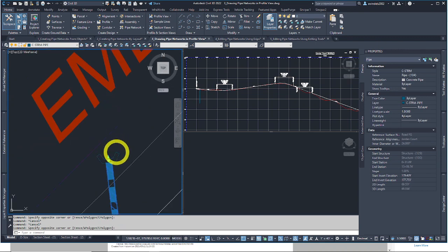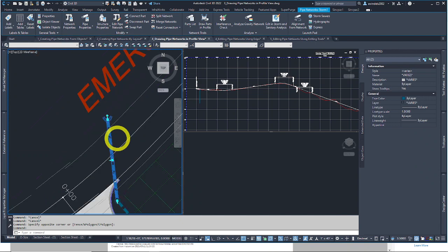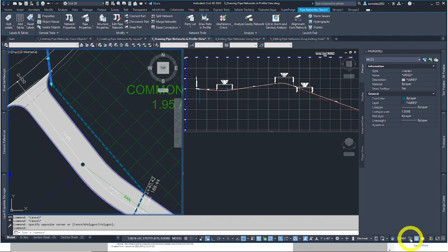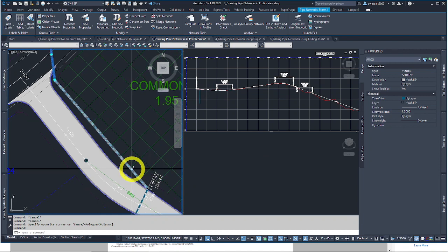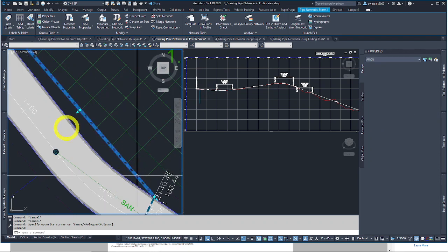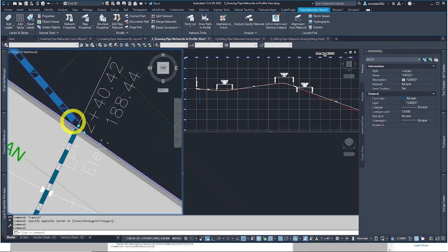It didn't really instruct you to add these structures and pipes, so I'm just going to see how it looks. I'm curious. Grab more pipes. You can use isolate objects and hide objects to more quickly isolate Civil 3D objects along with AutoCAD objects. That might be a quicker way to select a really complex network that's snaky and has hundreds of vertices and pipes and structures to pick. Ours is not that big, so we're just going to do it manually instead of isolating things.